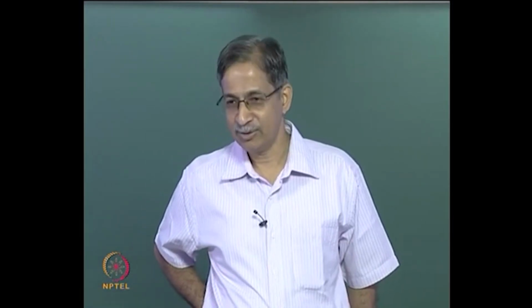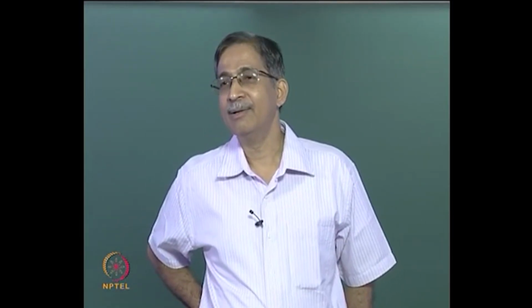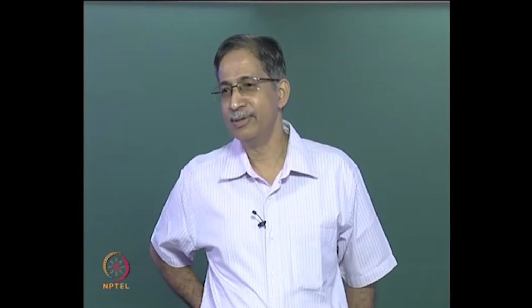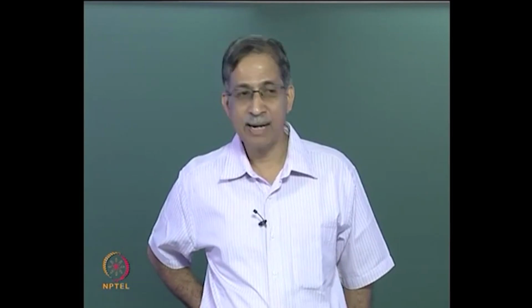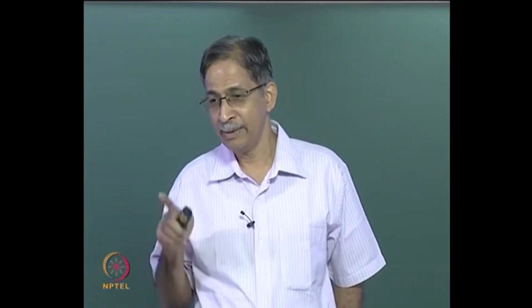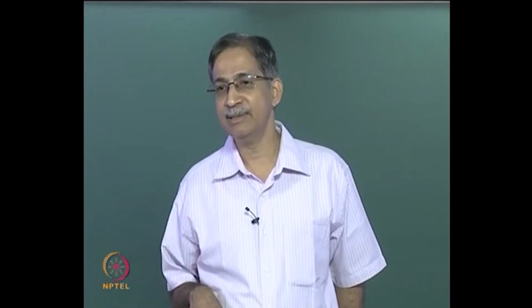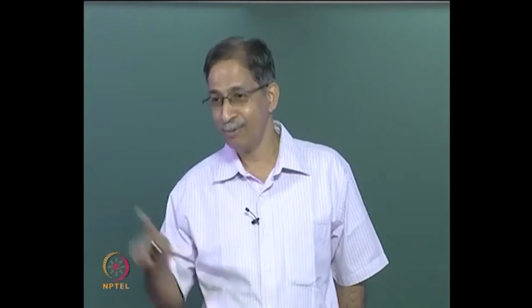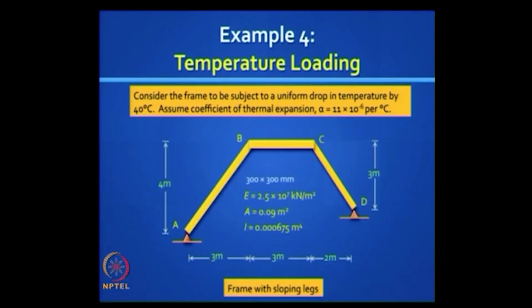or slope deflection method, not moment distribution, because moment distribution is not good when you have sway. You will find that they are almost identical. This is more accurate because you are accounting for axial deformation. We will do the same problem by the reduced element stiffness method, where we ignore axial deformations, and compare the results. Okay, here is one last problem, a really interesting problem.